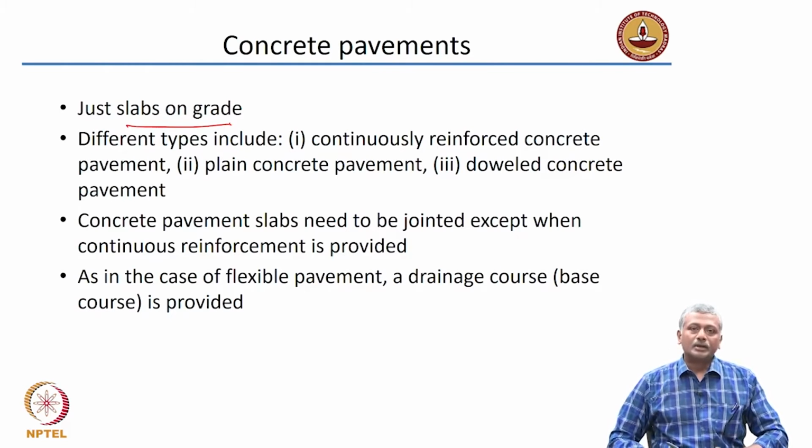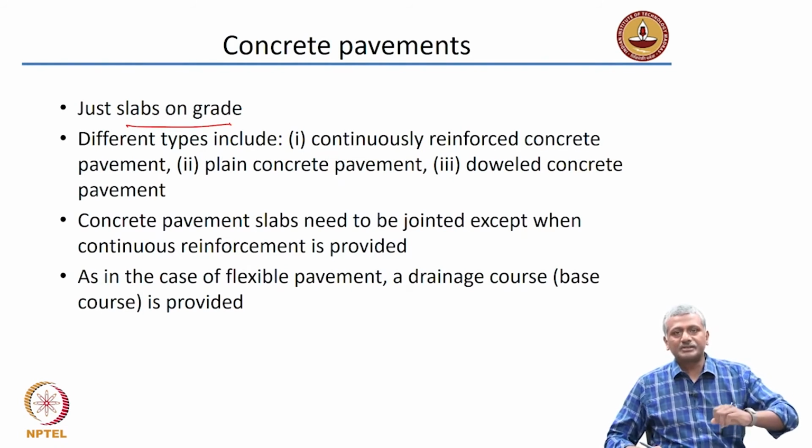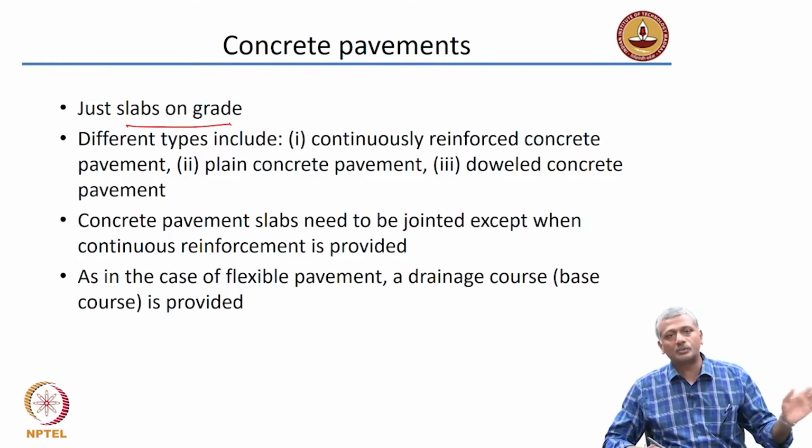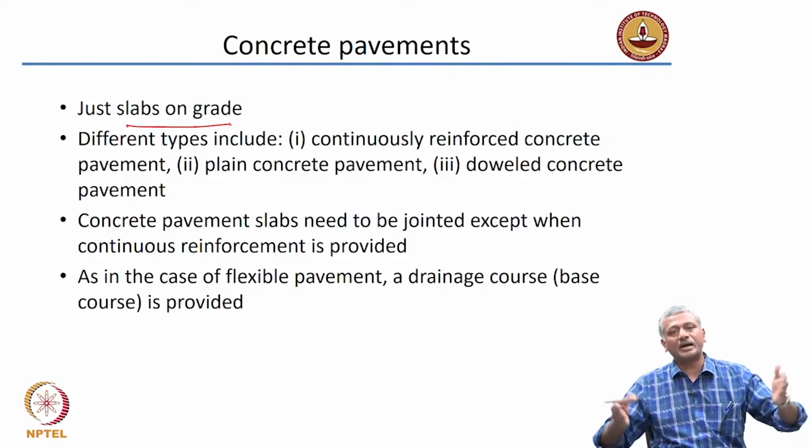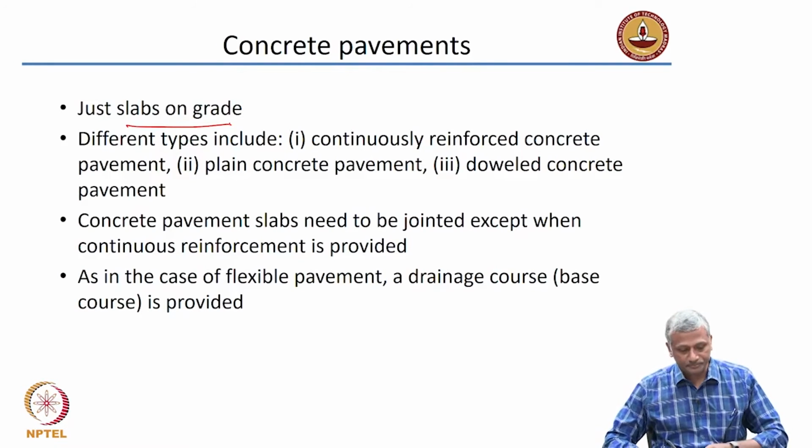Now, of course, you don't place it directly on the soil. You need to prepare the surface first, and you need to also have granular material as a base course, just like what you did with the asphalt pavement, and then you have the concrete slab coming on top.